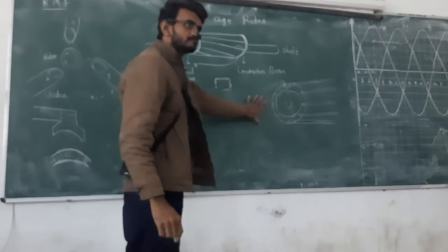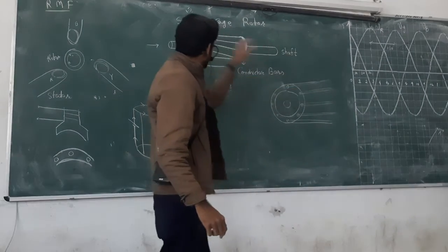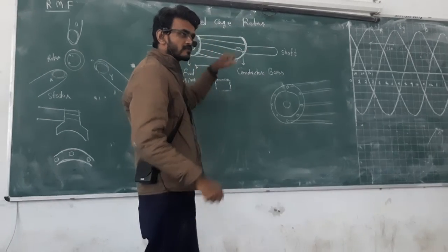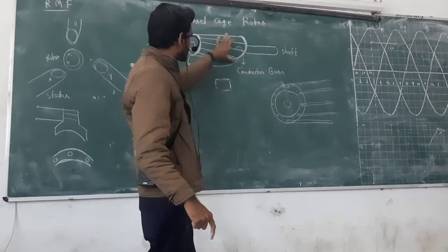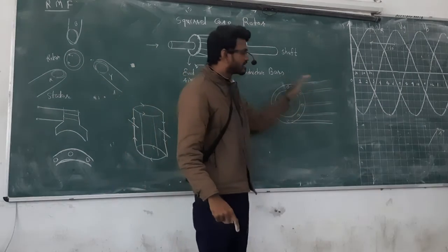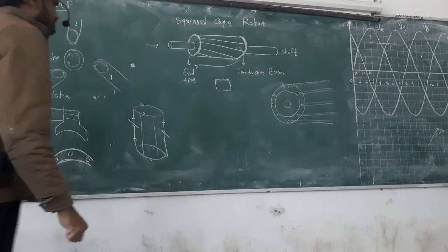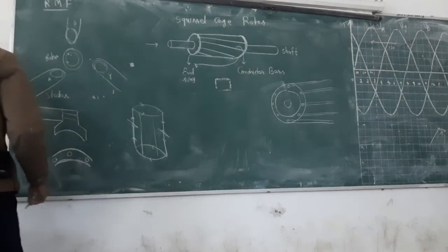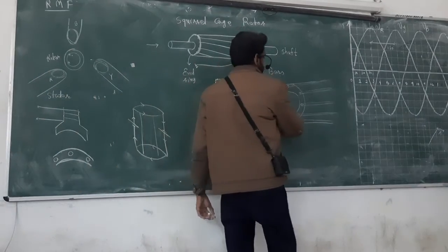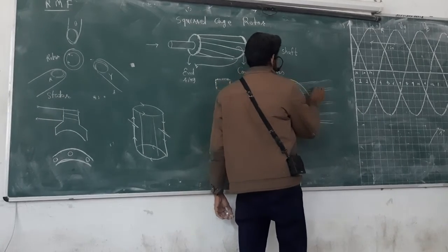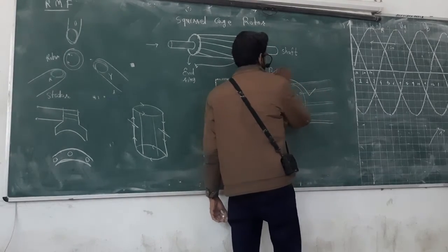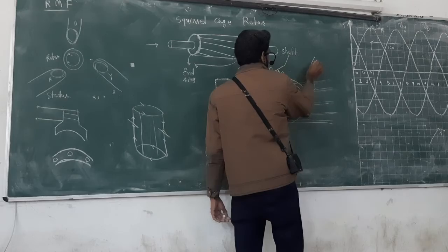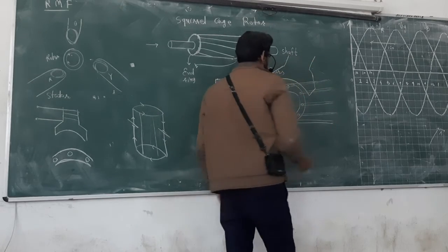This kind of rotor is there, a squirrel cage, and the bars are skewed, not perfectly parallel. That we will discuss later. Why is this happening? It's an engineering trick: if you want better sinusoidal operation, then you have to put in this skew. But right now consider they are parallel. Okay, and the pole is here. So this is the picture.